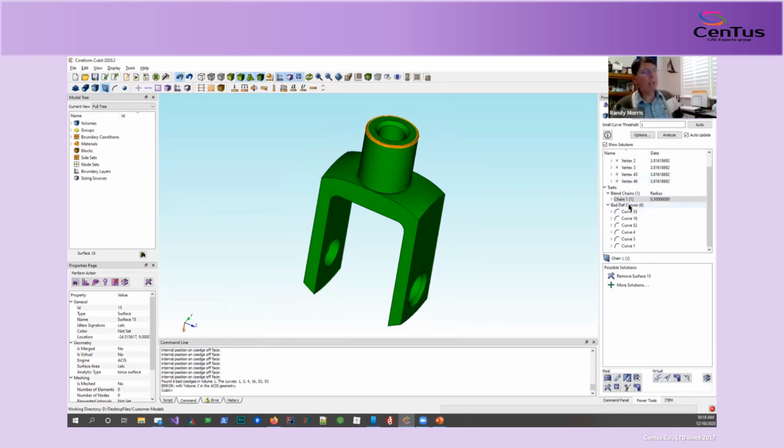When we have things like badly defined curves or badly defined surfaces or whatever, one thing we recommend is always doing this. When we import a model, and Carl, correct me if I'm wrong, we want to run what we call an auto healer. Our solid model kernel is from Spatial. It's the ACIS kernel. Spatial also is owned by Dassault now, and they have a healer kernel in their solid modeler that will look at these badly defined curves. It's ACIS that told me these curves are badly defined, and ACIS can do some things to clean them up.